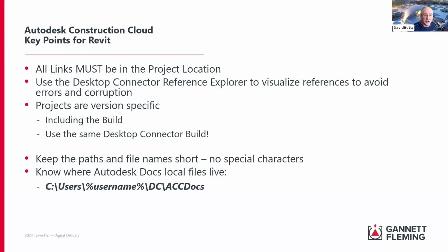Spend the money on your internet access and make sure that it's fast, because most failures occur when a Revit model cannot communicate quickly enough with the cloud. And here's a trick question for people out here that you can put in the chat. Is Revit, the RVT file, the only thing that talks to a model in the cloud? When you save an RVT file, is that the only thing that's being saved up to the cloud and the only thing that's communicating to the cloud? And the answer is no.